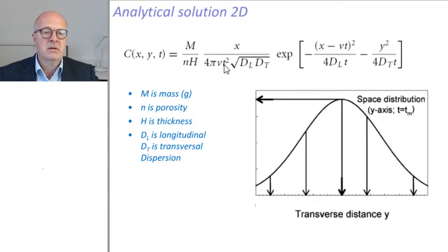So I solve this equation for any time from 0 to 86,400 seconds, so for a full day. This is given by flow velocity and by distance x. This as well, it's 1/10 of this value basically. This is a constant, this is known, this is a variable, and so on, and I can actually get a nice plot of my breakthrough curve at 100 meters below my injection point.